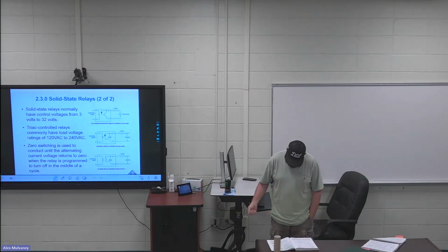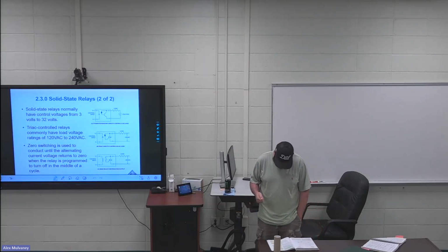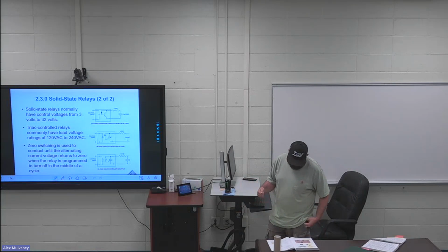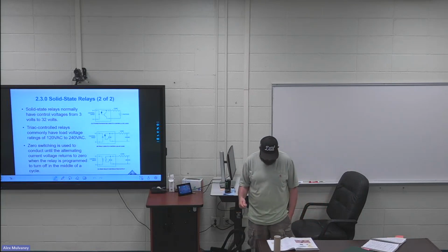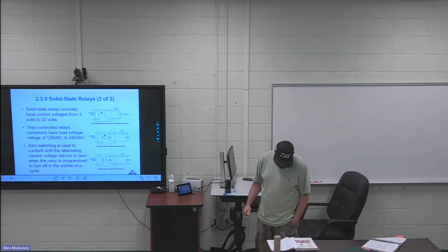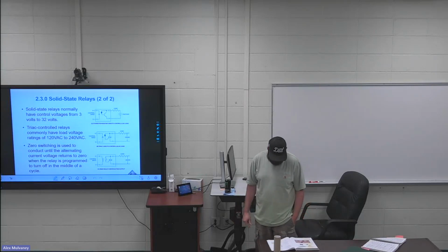With a light emitting diode, LED, connected to the input or control voltage. This is a common circuit arrangement in solid state relays, and relays that use this coupling method are referred to as opto-isolated because the load side of the relay is optically isolated from the control side of the relay. Since a light beam rather than electricity is used to control the relay, no voltage spikes or electrical noise produced on the load side of the relay can be transmitted to the control side of the relay.